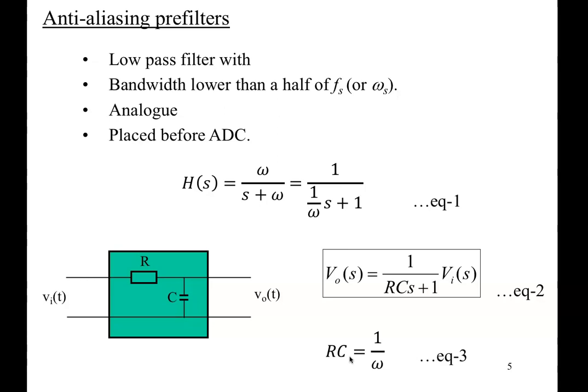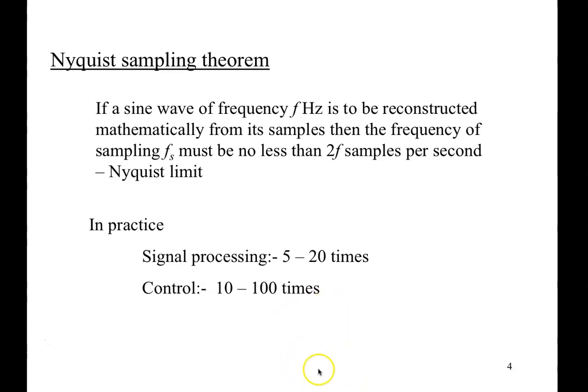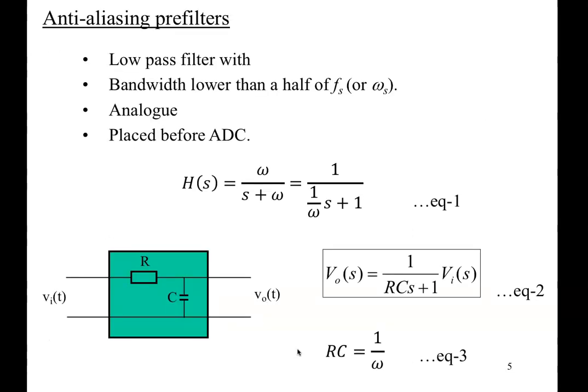So that's how you determine the sampling interval from sampling frequencies, and the guideline in practical terms is towards 100 times. Okay, between 10 to 100, but towards 100 times of the maximum frequency you have to deal with in the system. So you choose that sampling frequency, you half that to design your filter. And then you invert the sampling frequency to give you the sampling interval.